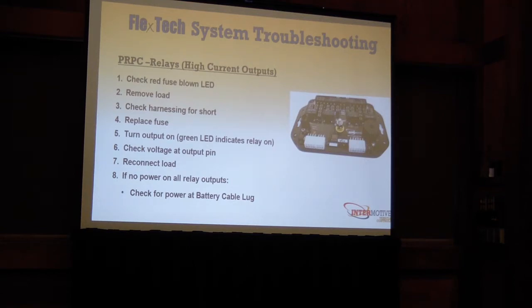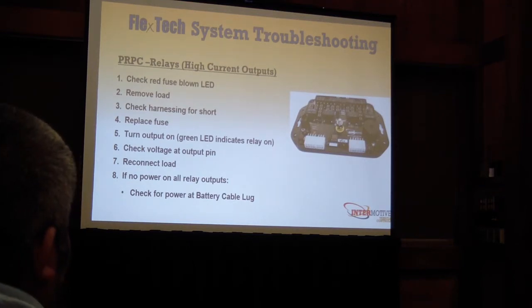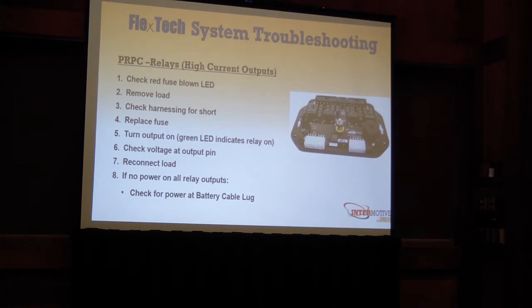You just program it into the module and provide a single output that does what you need it to do. So if you want to do park brake set, transmission in park, and ESS less than 2, you can do it with a single output. You just program it on the module.